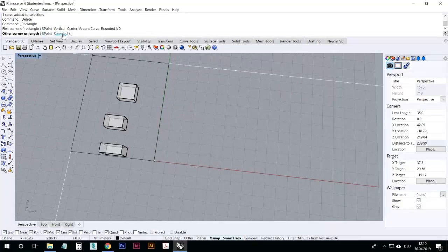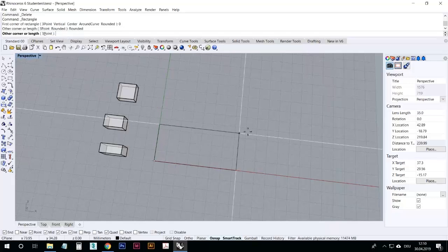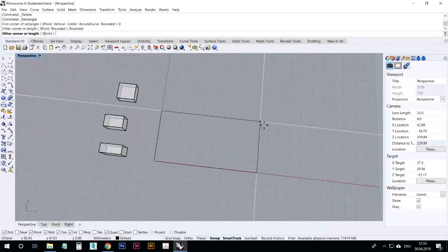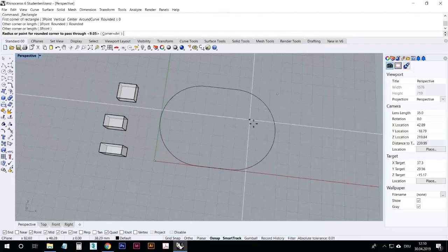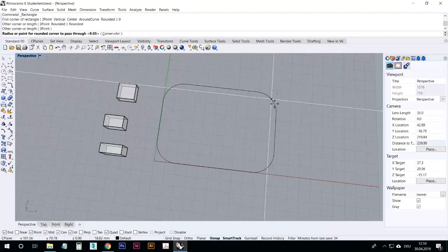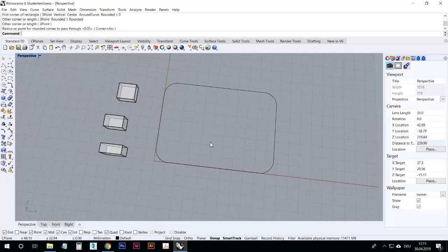If you click rounded, it's something that's very useful. Then you tell it already that it's not supposed to have sharp corners. So you see a preview from sharp corners, and then another option comes. You can type it in, the distance. That's the radius of the half circle, which is being built in the corner. So you can just simply do mouse like that.